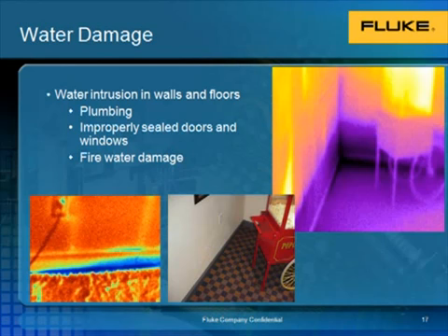Here's another example of water damage within a home. The image in the upper right is of a basement that is recently flooded. Now, even though there may have only been an inch or two of actual standing water, the sheetrock and insulation has soaked up that moisture about a foot or two up the wall. By using the thermal imager, we can easily see how far up the wall we have an issue.